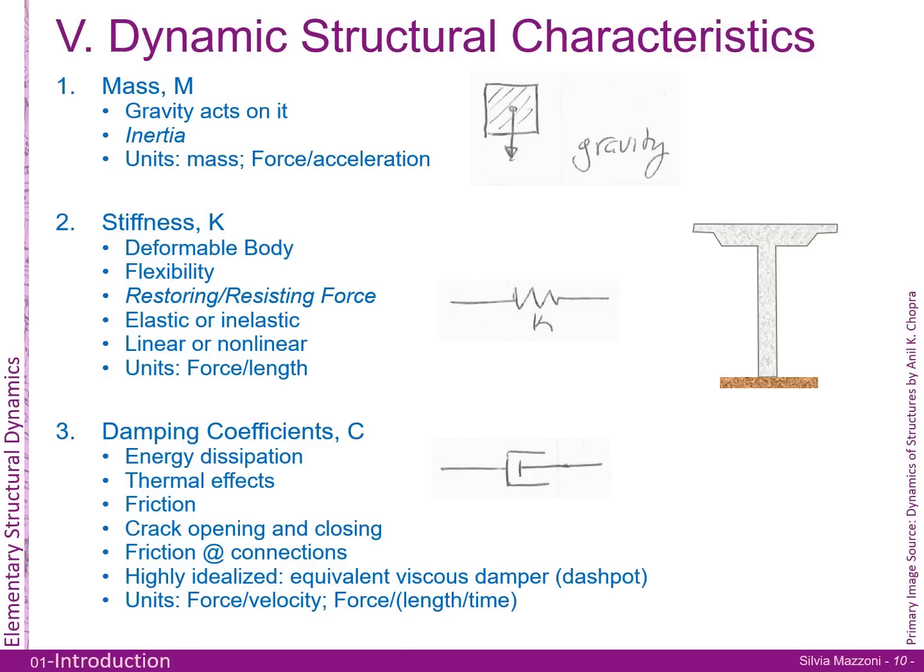And mass is twofold. First of all, gravity acts on it. So you always have to put gravity into your equilibrium equation. Make sure that you account for it. Sometimes it's going to fall out of the equation. You'll see that it's not always important, especially because it's not always in the direction of your loading anyways. But it's something that you always have to think about, where is it with respect to this? And what really matters in dynamics is the inertia, which is the force that your system resists because it doesn't want to move. Newton's second law says that if you want to move an object and change its momentum, which is mass times velocity, you have to apply a force to it, whether to bring it from 0 to something or from something to 0. So if you want to accelerate something or if you want to bring it to a stop, you need to bring in a force, and that's equal and opposite to your inertial force.